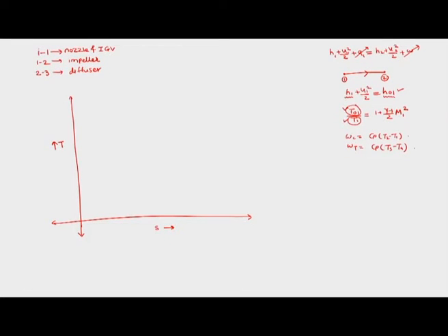Since kinetic energy is negligible in terms of enthalpy, we had neglected the total temperature and instead considered the static temperature. But now we have to consider the complete energy, where we have to consider the kinetic energy as well. So if we consider kinetic energy, then compressor work will be treated as Cp into T02 minus T01, and turbine work will be treated as T03 minus T04.